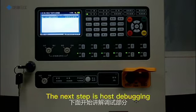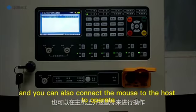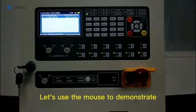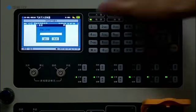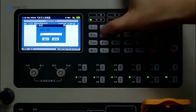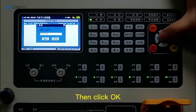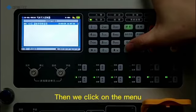The next step is host debugging. We can debug through the operation panel key, and you can also connect the mouse to the host to operate. Let's use the mouse to demonstrate. First, we hit the star key. Enter the password 26582231. Then click OK. The keyboard light is lit. Then we click on the menu.